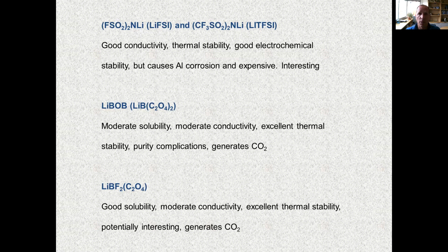The biggest problem with both of these two salts is that they cause corrosion of the aluminum current collectors. And so as I mentioned in the first presentation, the current collector on the cathode side is aluminum metal. If you use either LiFSI or LiTFSI, these corrode the current collector, damaging the current collector and effectively damaging the cell. So this is a significant problem. There are some ways to avoid this problem, but in most electrolyte formulations that are primarily composed of LiFSI or LiTFSI, this continues to be a limiting factor.